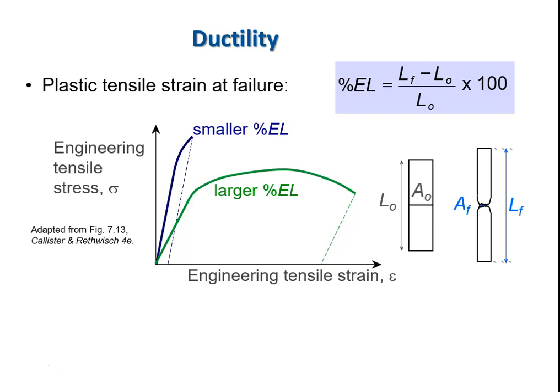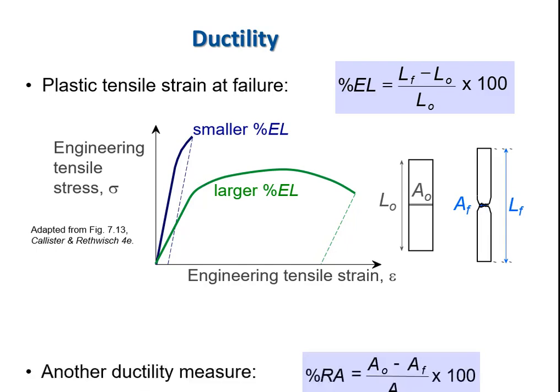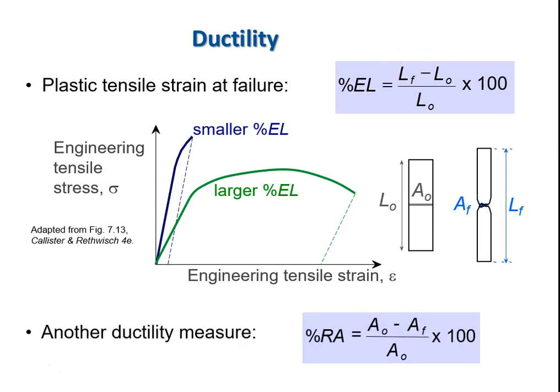So if somebody says, I did a tensile test and I got a 50% strain at failure, what's the ductility? 50%. So it's really, really easy. So there's ductility defined on the upper right in terms of length change, and then in terms of area change.